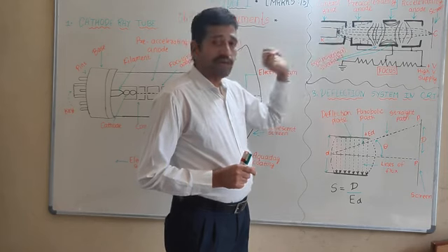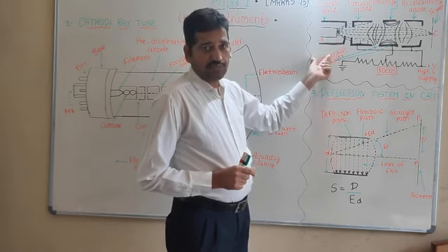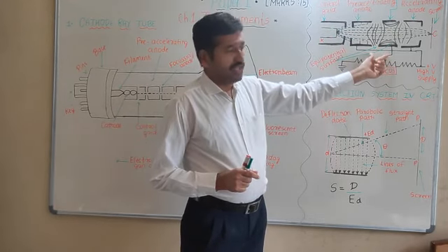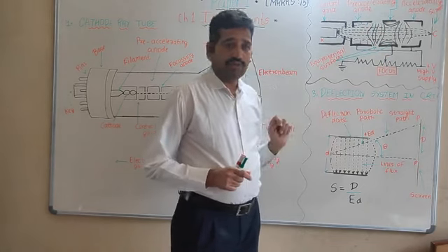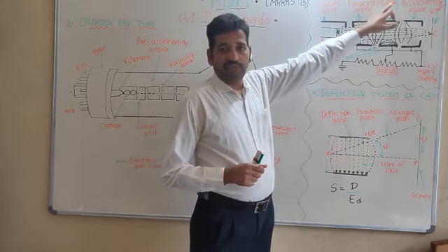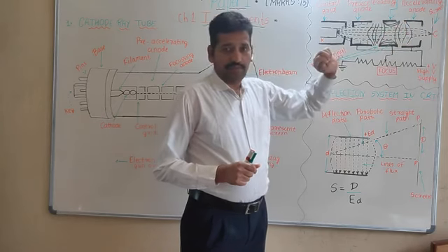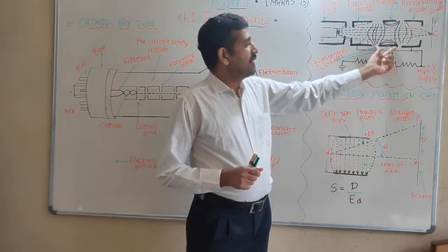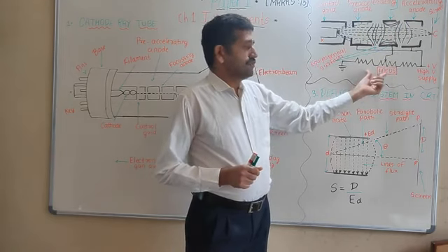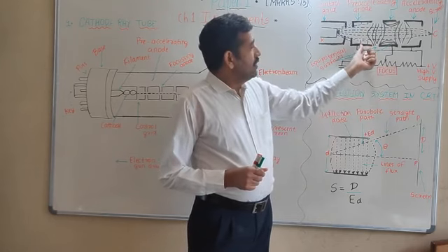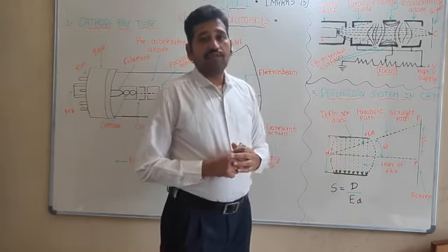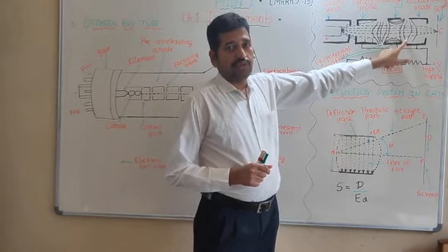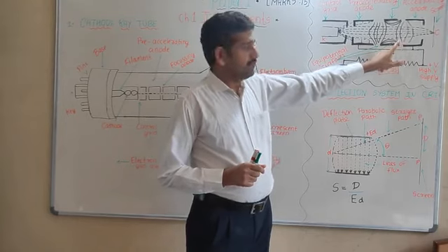These voltages can be controlled by using external controls like intensity and focus. Now there are three anodes: pre-accelerating anode, focusing anode, and accelerating anode. By using a variable potentiometer, we can vary the focus control. Here, equipotential surfaces are formed due to the voltage differences. It shows a concave lens effect.